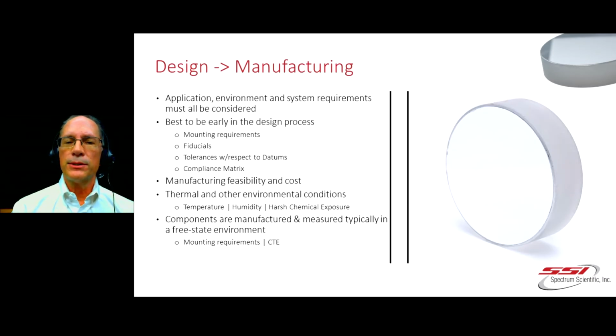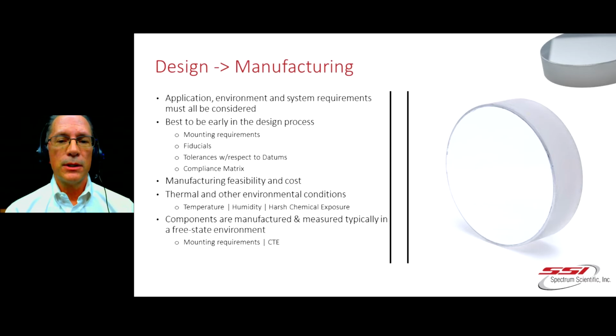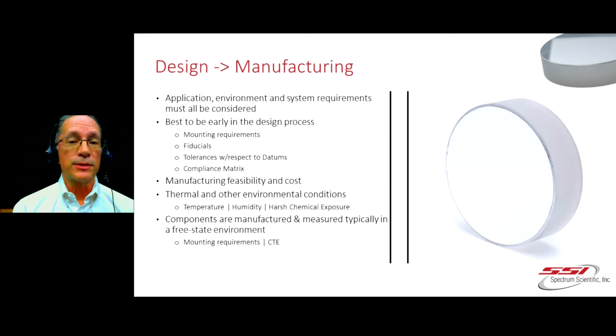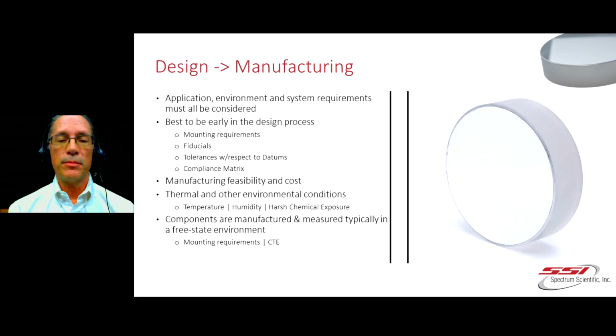It is really good to leverage the advantage of replicated optics early in the design phase so that optomechanical features can be determined. I know a lot of people who put parabolas into their systems always put a wedge back parabola in, but a parallel back parabola is much more cost effective in manufacturing and much easier to make.